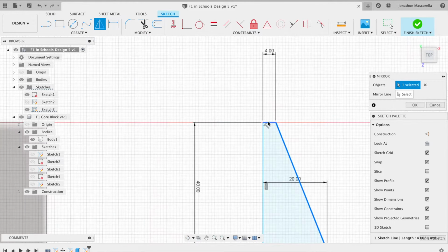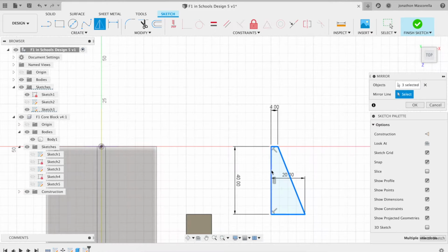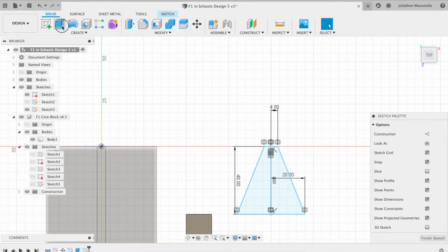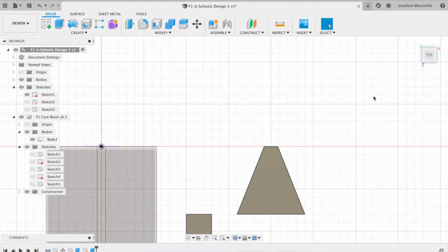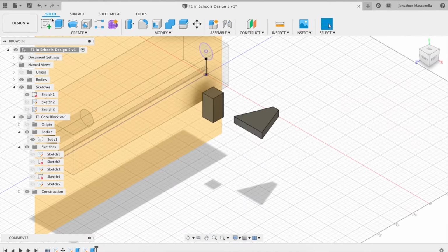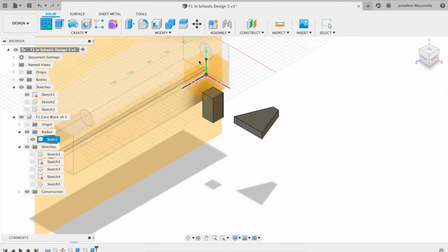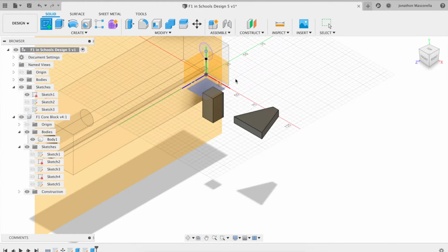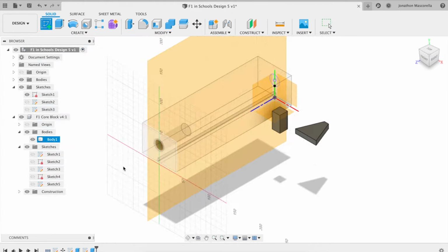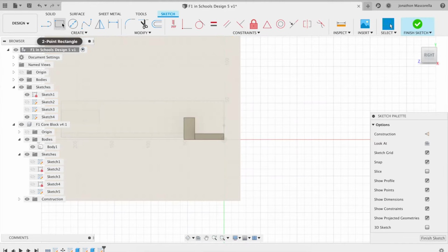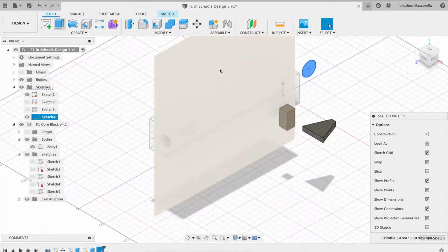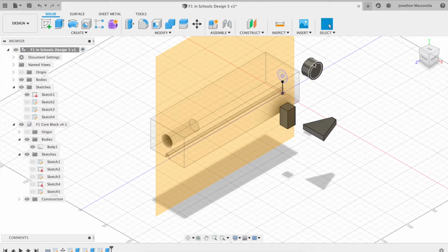I don't fix it in this particular instance, and that's because this is just an example, but of course I probably just have to make the side pods a little bit thicker, or widen the body of the car at that point, but neither of those is a massive deal. I can always edit earlier sketches to make sure that I bring the side of the car out underneath those pods. So let's create some duplicates of this very quickly, create the wheels, and we're going to insert all of these components into the block in the correct places.